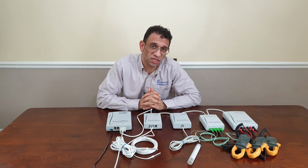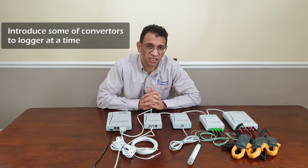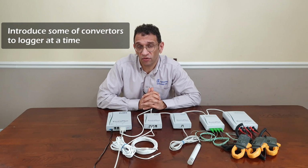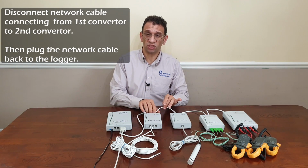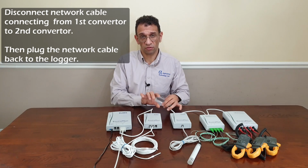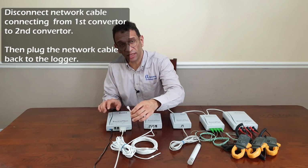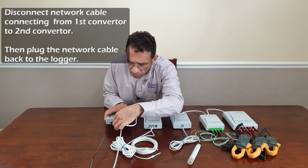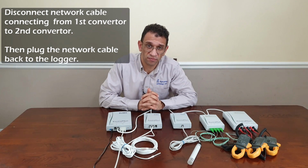So what we're now going to do is to introduce some of the converters to the data logger at a time. So in this case, I'm going to introduce one converter at a time to the data logger. So the first thing we need to do is to disconnect the converter cable connecting the first converter to the second converter. And then we can plug in the converter cable back into the data logger. And then wait a few seconds. The first converter should appear.